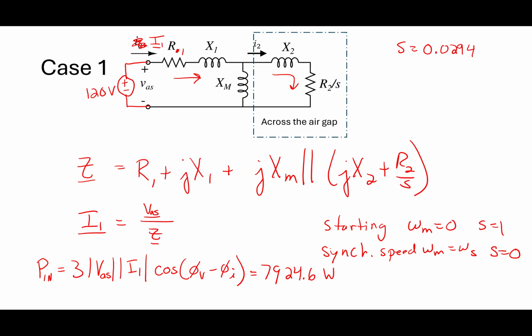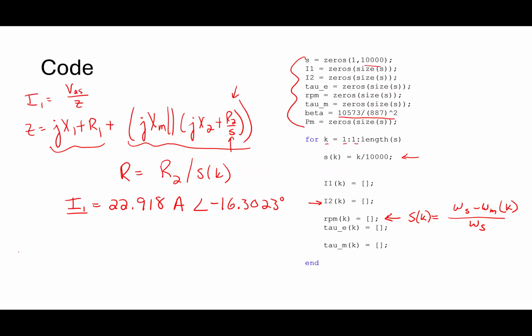Okay. Now, when I ask for the efficiency, it is what over what? Efficiency of anything is what over what? Yeah, it's always output over input. So I would put P mechanical, that's the actual power delivered, divided by whatever P in is. Now, I said my mechanical power is 10 horsepower, but I obviously got to get these in the same units. So I switch them over. When I do that, I get that the efficiency is about 94.17%.